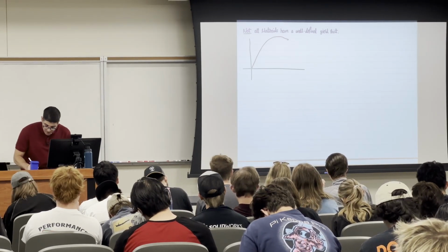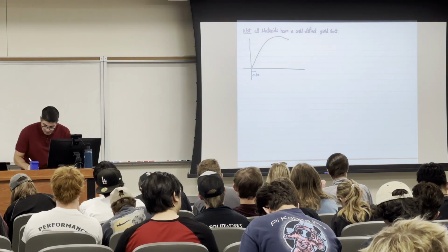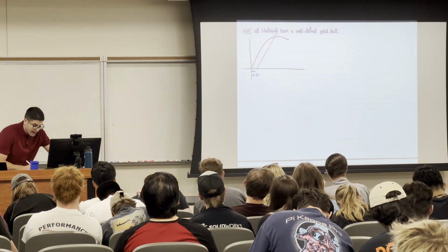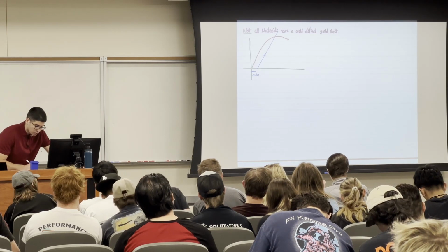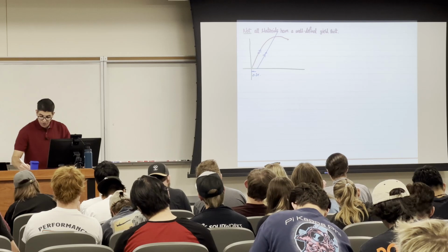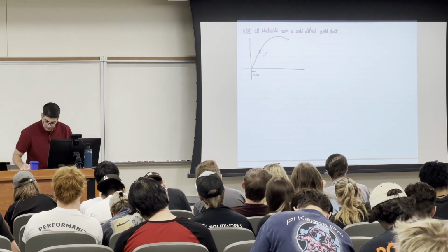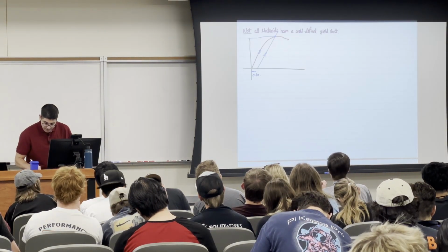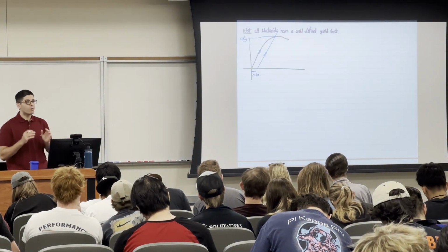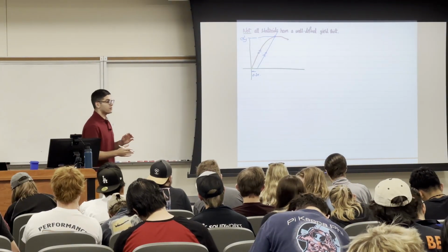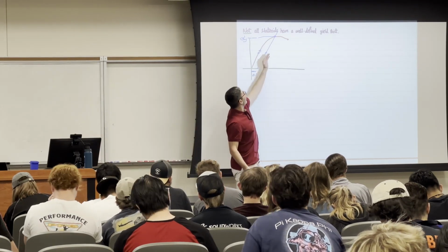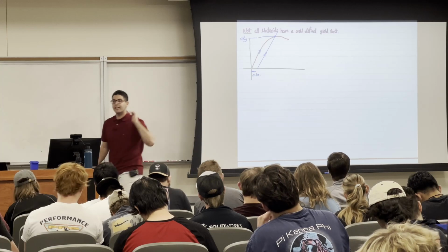We go here by 0.2%, and we make a line that is parallel to the linear line. Wherever this line crosses the curve, that's our yield. Okay? When you don't have a well-defined yield point, you offset by 0.2% here and draw a line parallel to the linear line.